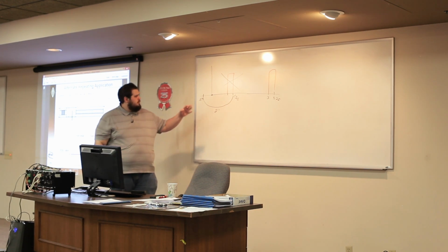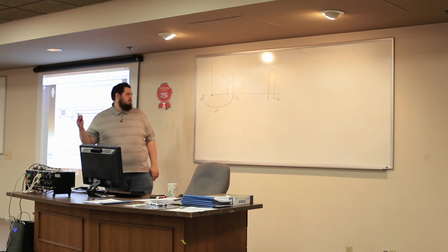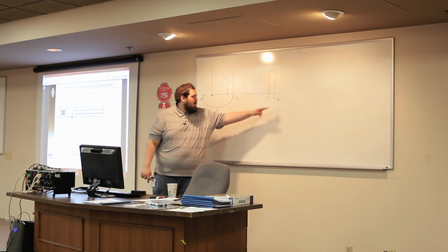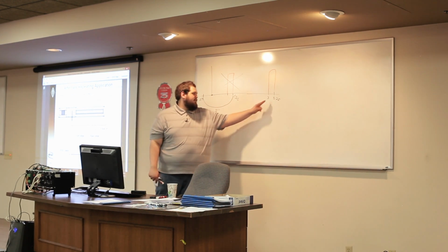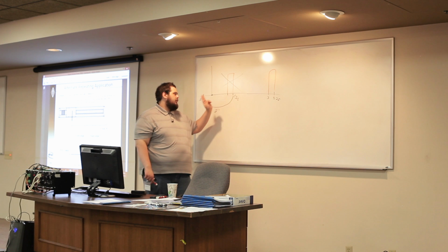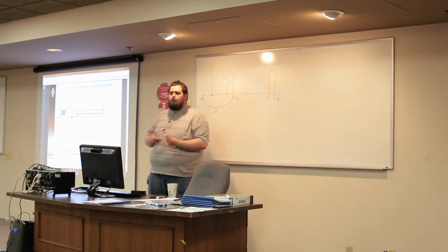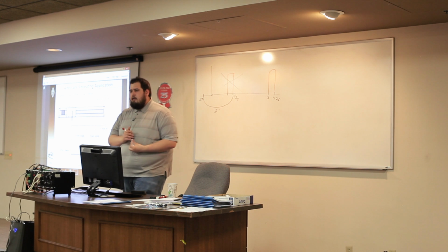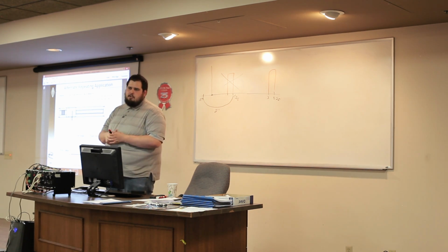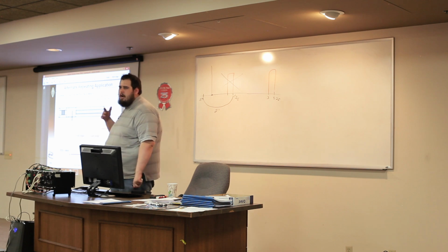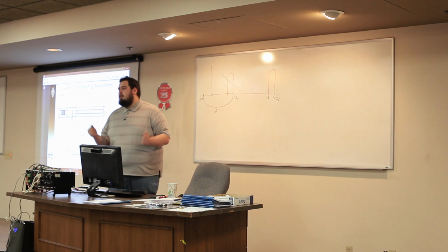So in order to set up my comp A and comp B so that I'm in between them, I would need my comp B to be all the way back here. And then the issue is, as soon as I hit 3, my comp B would still only increment one time. It would end up right here, and I'd be outside of my register, so I wouldn't actually get the pattern at all. Now, if I'm not doing auto-incrementing, this also isn't an issue, because I just set up wherever I want my one pulse. Doesn't matter if I'm anywhere near there or not. It'll turn on, it'll turn off, and everything will be done.